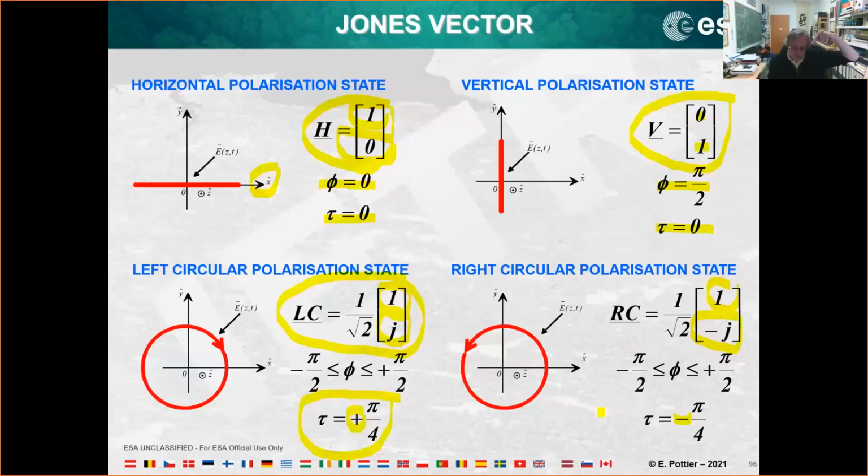So like that, you can analyze the sea surface, and you can see that if I transmit a given polarization, what will be the polarization back? So like that, using this relation, you can have the information about the polarization which is coming back to the radar. If it is a circular polarization, if it is a linear polarization, if it is a left-handed, a right-handed polarization, etc., etc.